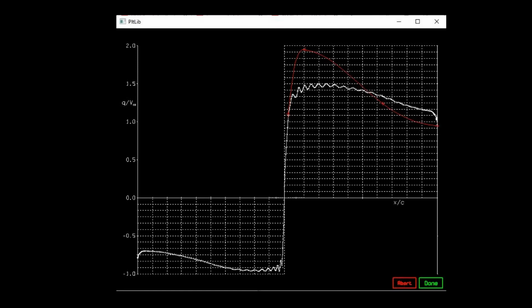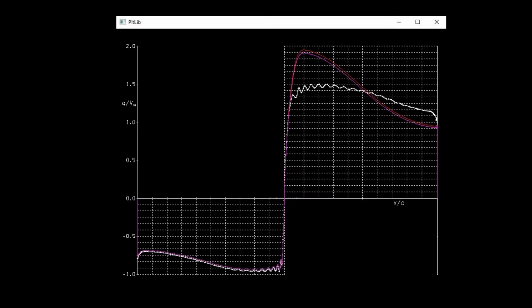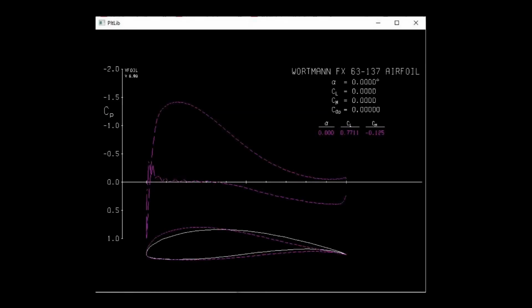However, Xfoil has one big advantage. It has the ability to use inverse design methods, where the pressure plots can be altered and the wing profile adjusted to match the pressure distribution. This is an important method for profile design, and it has been used to develop a lot, if not most, high-lift wing profiles. A little background on Xfoil and the inverse design method.